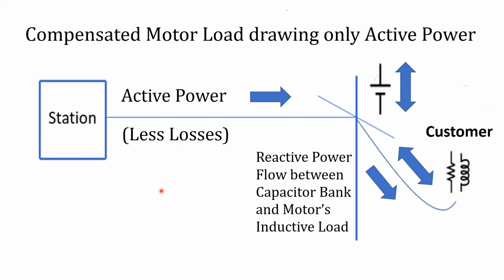To summarize then, while it may seem like a small point at first, the result of adding capacitors to compensate for inductive loads is the elimination of the losses that the extra reactive current wastes in the conductors. And this results in a huge savings for the utility.